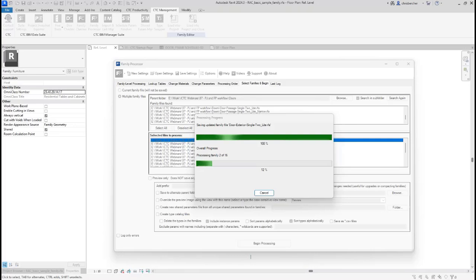also using the same parameters from the parameter file that you've mapped, right? So what the tool is doing is it's scanning the schedule for shared parameters found. Then it's also checking that against the shared parameter file that you've mapped in Parameter Jammer. And if they align, there's your report, and that's what you get access to for parameter swapping. If they don't align, you're only going to get the ones that do, or only the built-ins. So that's the first place that I would go to check.